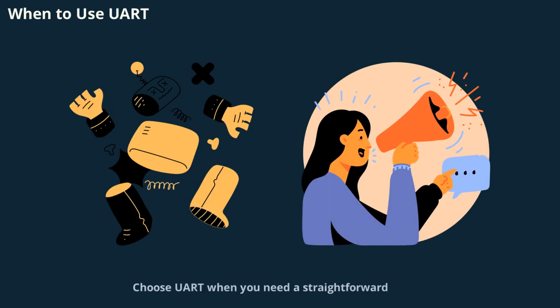Choose UART when you need a straightforward point-to-point connection between two devices. It's ideal for simple communication, like linking a microcontroller to a GPS module or Bluetooth chip. UART's simplicity means fewer wires and easy setup, making it perfect for beginners or small projects.